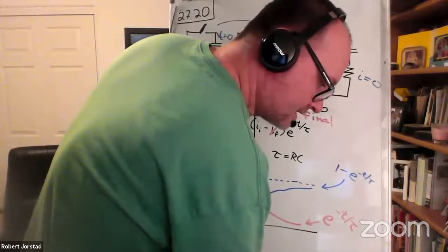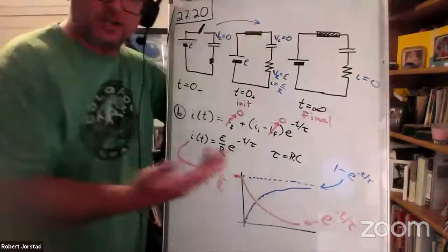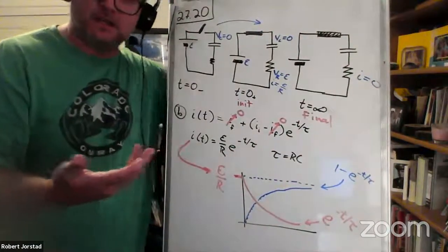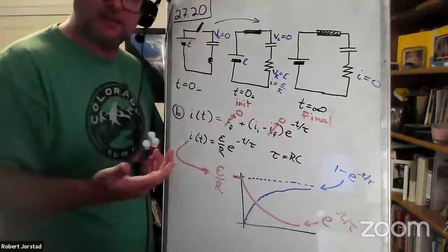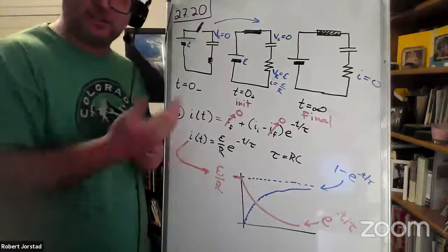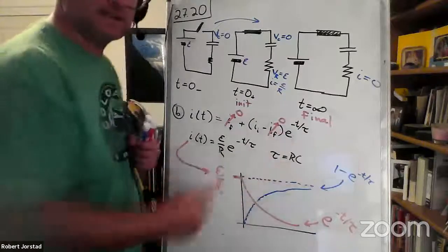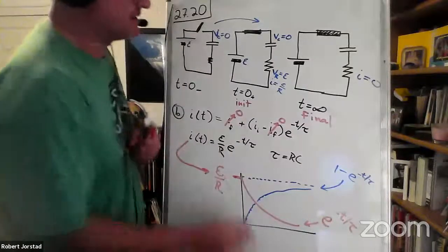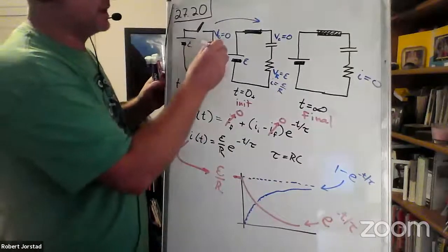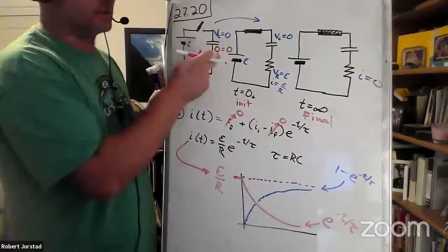All right. And so now, let's see, find current and resistors. Okay, so we've done that. Find charge on the capacitor as a function of time. If you had to guess right away, charge is going to start at 0 and grow. So it's probably going to be like this blue curve. So we're expecting a 1 minus. If I go back up here to my original results, I know that Q initial was 0 because there was no charge.